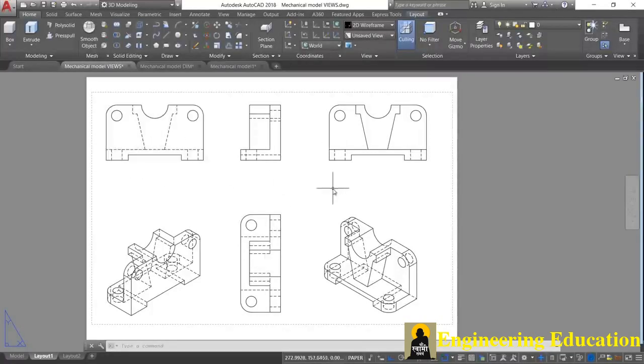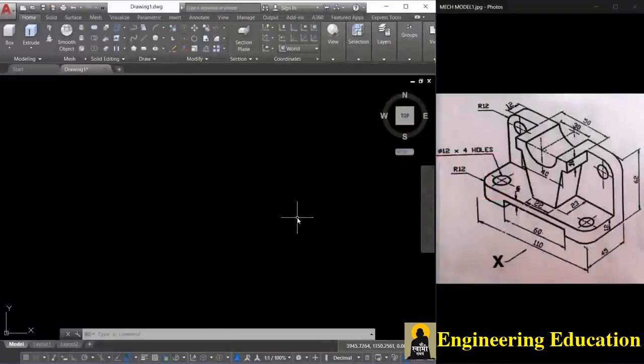Then we will also see the procedure to create drawings from the 3D model. We can have elevations, isometric drawings, as well as get started with the 3D modeling part. And this view is in fact a southwest isometric view. If you need any clarification related with the view generation in AutoCAD, please refer my Introduction to 3D Part 1 video in my channel. I have provided the link in the upper right corner as well as in the description section. Now let's go to southwest isometric view by clicking on this hotspot of the view cube.